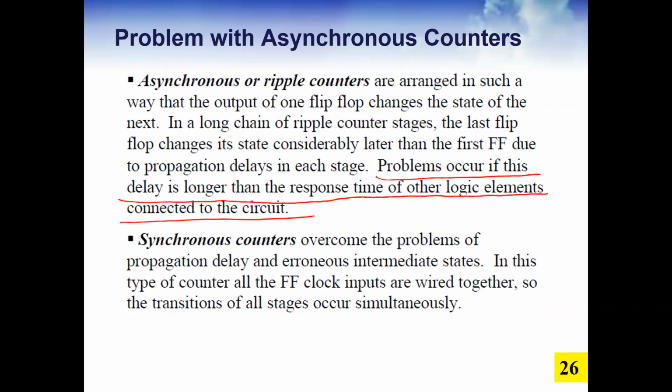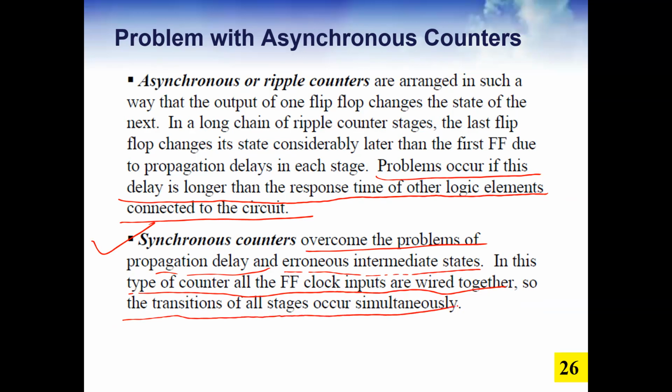connected to the circuit. So how can we eliminate this problem of propagation delay? The solution is the synchronous counters. Synchronous counters overcome the problem of the propagation delay and erroneous intermediate state. In this type of counter, all flip-flop clock inputs are wired together, so the transitions of all states occur simultaneously. So we'll discuss now synchronous counter design.